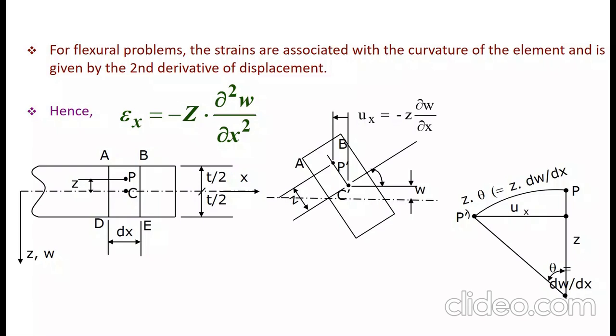For this, the beam has a thickness of t, and the load is acting with respect to the center point at some z deviation. Taking a small cross section of dx, when applying loads, the deformations will occur at different angles. The deformation will be considered as w, and then the slope will occur based on w, from the initial point to the final point. It will move forward as u of x, which will be called theta.